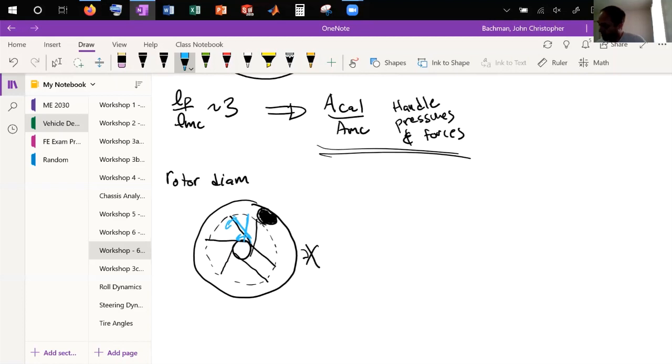And so at this point, you've got the outside, you start to look at your rotor connection, you try and get this thing as thin as possible, right? Based on what you can handle in terms of making sure it doesn't overheat so that it's melting, and also so that it can handle the stress that it's imposing. You're designing the spokes so that you're handling the stress. Definitely you're putting radii in your spokes, right? So this is a solid piece. It's got radii here, it's got radii here, right? So this is all solid up in here. You don't want any sharp edges, right? No stress concentrations at this point.